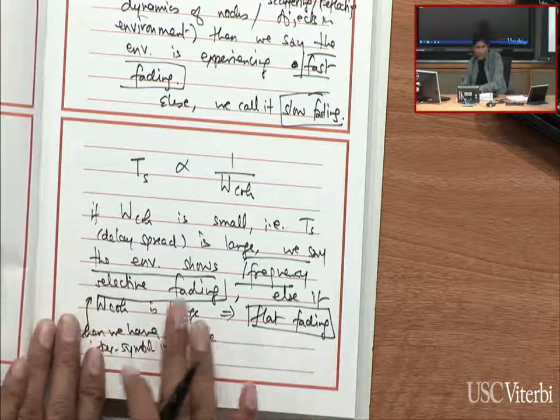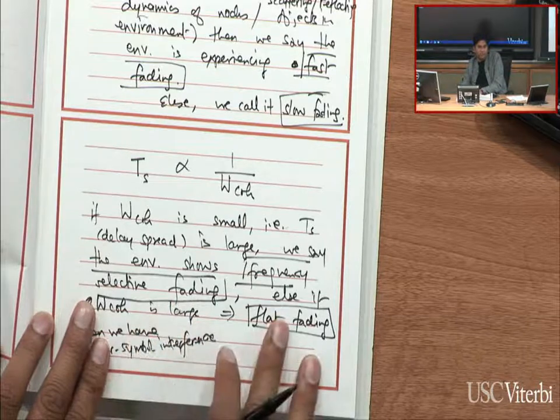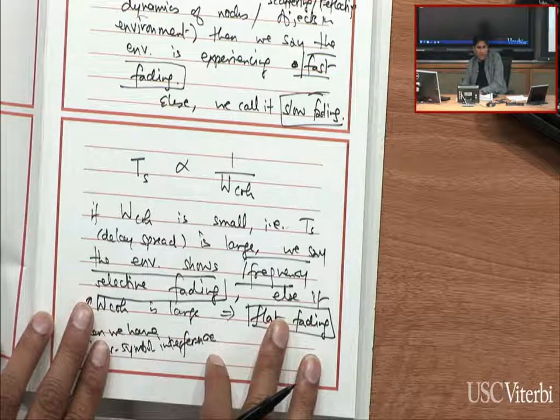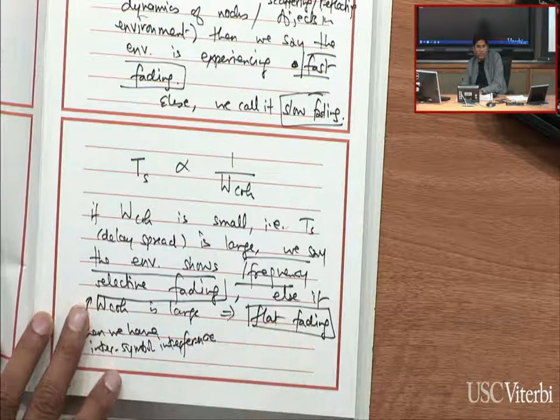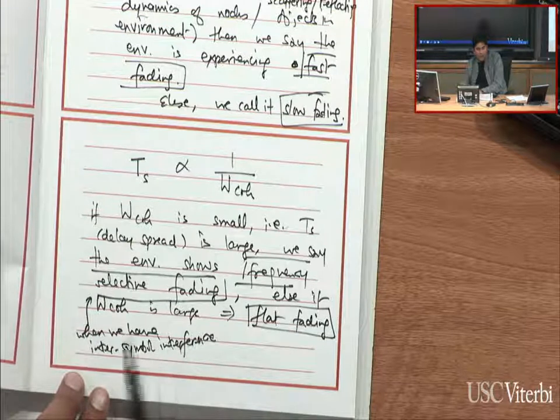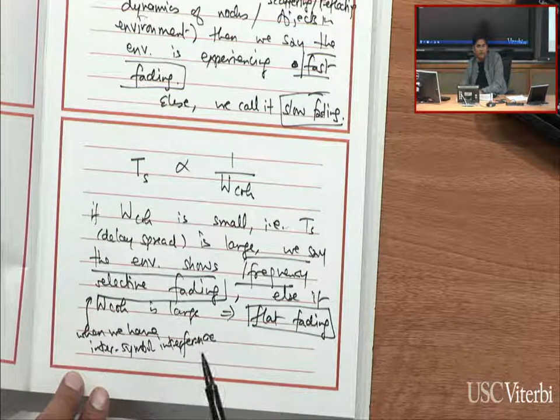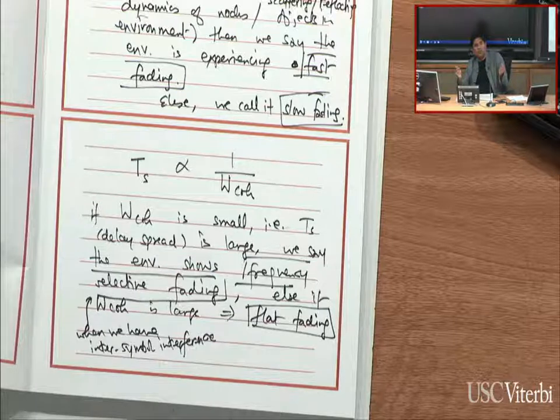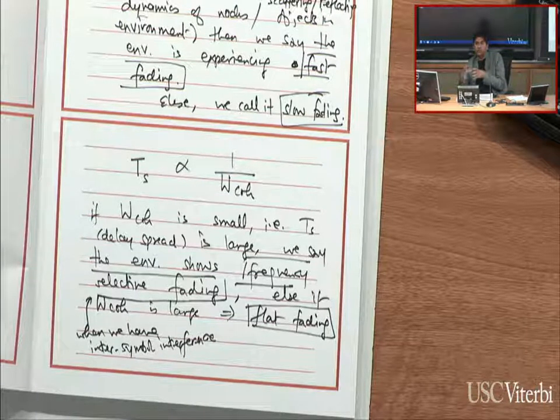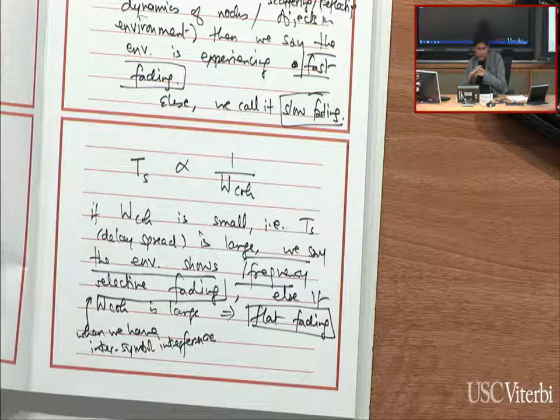And we'll talk about a couple of techniques that have been developed to deal with the delay spread issue. One is to reduce the possibility of intersymbol interference by splitting your stream of data into a bunch of different low-rate streams. And that's a technique called OFDM. A different approach is to use a spread spectrum algorithm.